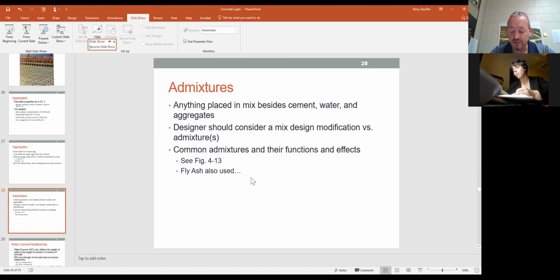And I'll talk about the water cement ratio later, but it enables them to pump it or work the concrete. So they don't have to even use it for pumping. If you had a very dense rebar mat that you would have difficulty getting the concrete into all the void spaces around all the rebar, then typically they would use a superplasticizer to help that concrete flow without segregation again.